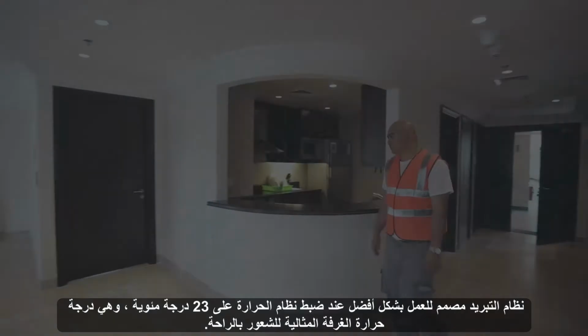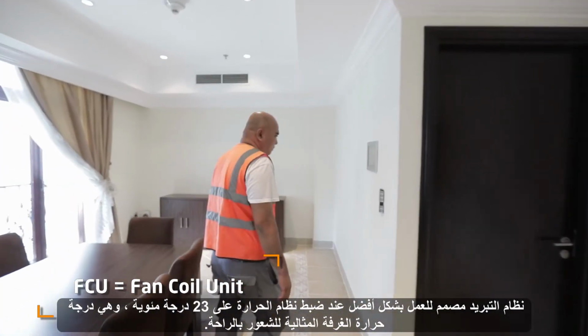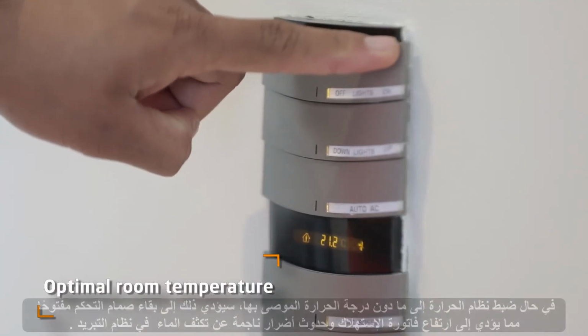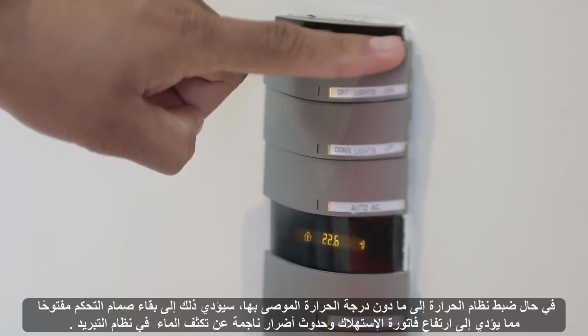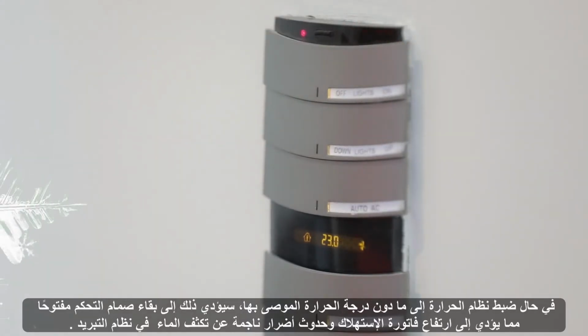The system, FCU, is designed to work best when the thermostat is set to 23 degrees, which is the optimal room temperature for comfort. Setting your thermostat below the design temperature will lead to the control valve remaining open, resulting in high consumption and cost with potential water damage due to condensation.